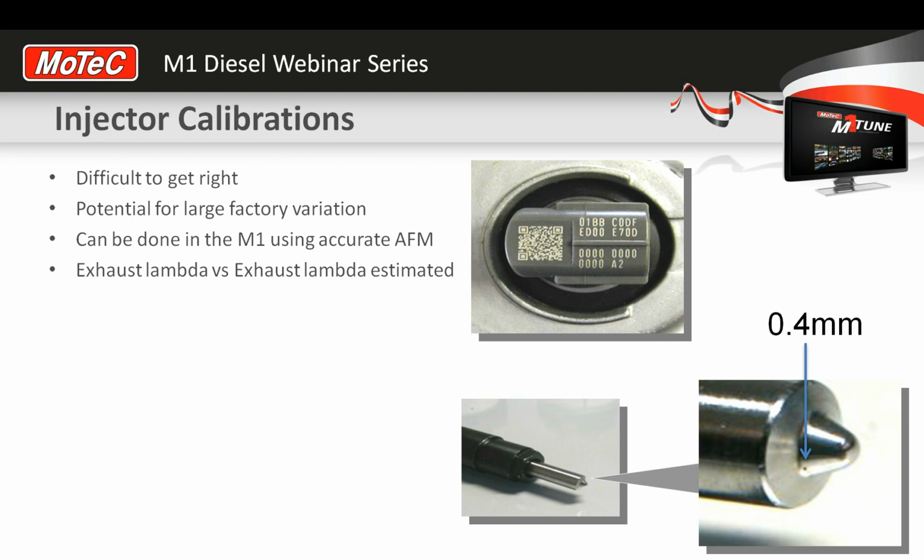So it doesn't stop you tuning it. You get the same result. When injector calibrations are really bad, you can have trouble getting pilots to phase in and out nicely without affecting power, but it is in the minor drivability stakes rather than the major. So certainly for racing, it doesn't affect you as much. It's only really for that lower drivability stuff.